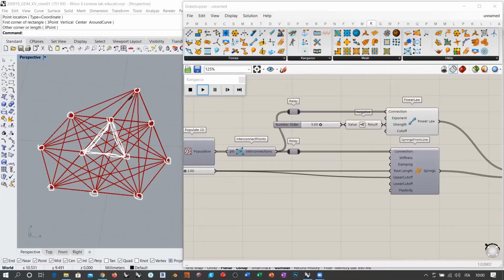That's because the springs only work when they get shorter, and when they get shorter, they want to go back to this actual rest length. When they are larger, they have no action. So if you have this spring here, this spring is not working at the moment. That's why you don't see the mandala effect in this case. As the springs only work below the rest length value, what they do is just expand in case the points get too close together. This avoids the points basically collapsing inside one single position.